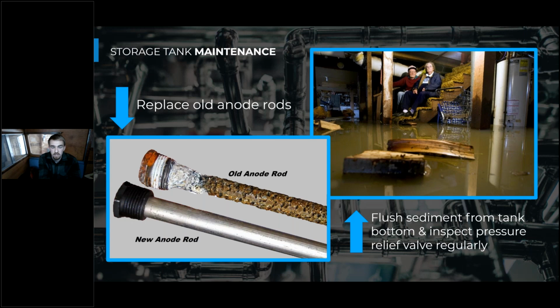And the secondary effect of that is anytime any of these components rupture, especially if it goes unnoticed, you could just have water freely running into whatever area your storage tank or your water heater's in, right? We have constant water pressure from the city, so there's nothing that's telling your water heater to shut down or block flow if there's a leak somewhere. So it's basically like turning a garden hose on and just putting that in your basement and letting it run until somebody notices.